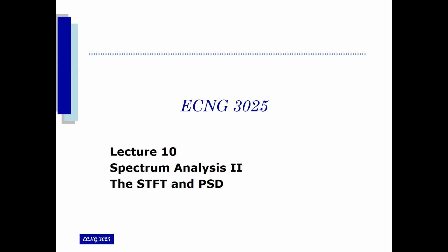Of course, I mentioned that the most common one used in most general purpose signal processing applications is called a Hamming window. And we saw that it was based on a cosine function, and although the spectrum was not ideal, we got a usable spectrum coming down that we could use to do our analysis with. And then we saw some other variations of that.